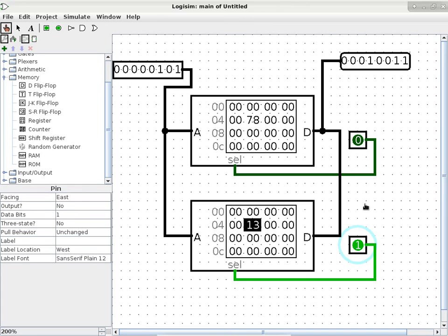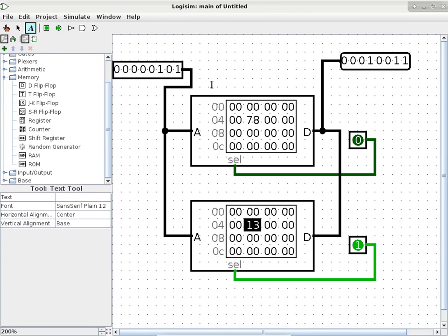So not displayed in this circuit would be a mechanism that will basically dictate which chip is responsible for which memory range or location range. So in this case, if I designate this as the first chip, then the first chip is responsible for location 0. This is all in decimal because we haven't really talked about hexadecimal yet. So this is from 0 to 255, and then this one is going to pick up from 256 to 511.